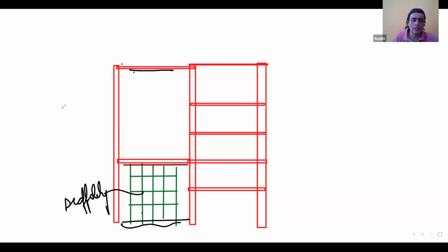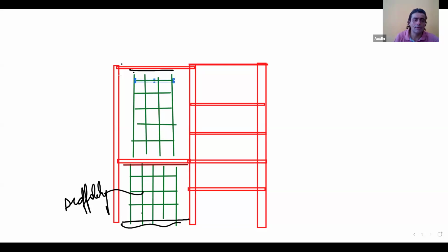Similarly, now if I have to do this slab, let's say this was a triple height, I have to first erect a triple height scaffolding, couplock system or whatever system. In this case, couplock will be the option. Then again, you will have to put your formwork. Then you will have to do the concreting. Again, this entire thing is stuck up. This space is stuck up, so to say.